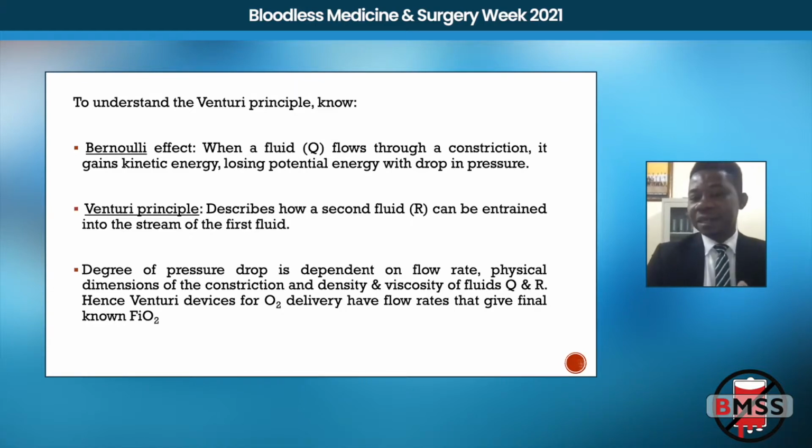Okay, the venturi mask has the Bernoulli effect and the venturi principle, on which it is designed. Now, when we're talking about the Bernoulli effect, it just helps us to know that when a fluid is flowing through a constriction, it gains kinetic energy, losing potential energy. So as a result of that, pressure drops. When this pressure drops, the venturi principle comes into play. The second fluid, that means it tends to entrain some stream of air into this already flowing fluid.